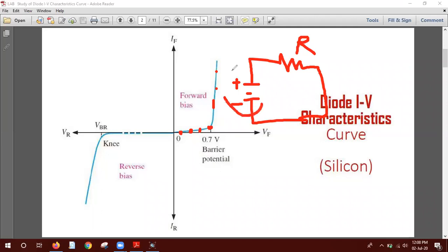Okay, so this is the voltage source, this is the resistance. If I want to measure the current, we all know that the ammeter will always be in the series circuit, my students, always in series. Because if you connect this ammeter in parallel, what is an ammeter? An ammeter is also a load, my students. An ammeter is also a load. Suppose we connect the ammeter in parallel.